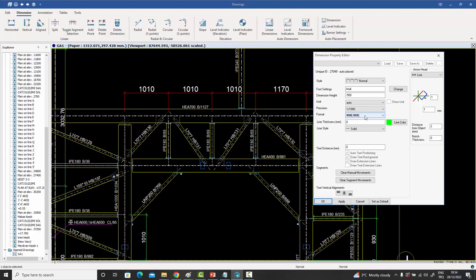And in the format section, you will see that in addition to the previous ones which we could use, now first of all you can choose them directly from a pull down combo box, but at the end you will see that there's this extra option of slash divided by slash. This is the one we will be using frequently. So let me just start off and give you an example. First of all, let me go to the feet option over here and say apply. And when you do that, you see that now those numbers have been changed, so it says it's 3.314 feet.